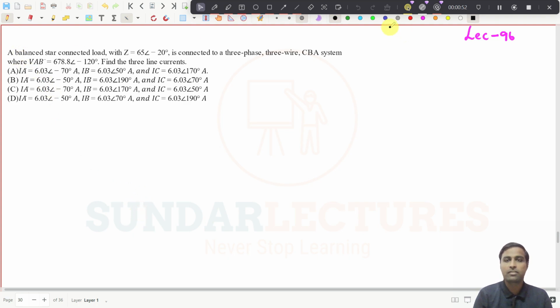This is the first problem. A balanced star connected load with Z equal to 65 at an angle of minus 20 degree is connected to a three-phase, three-wire CBA system where VAB is equal to 678.8 at an angle of minus 120 degree. Then we need to find the three line currents. This is the question they have given you.